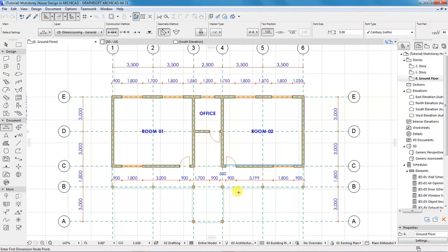to discuss a better way of labeling the rooms in ARCHICAD, which is by using the zone tool. Now if you notice, in our last tutorial we had labeled the rooms using the text tool. Unlike the zone tool, the text tool is 2D and does not contain a lot of information that can be used by other project team members.